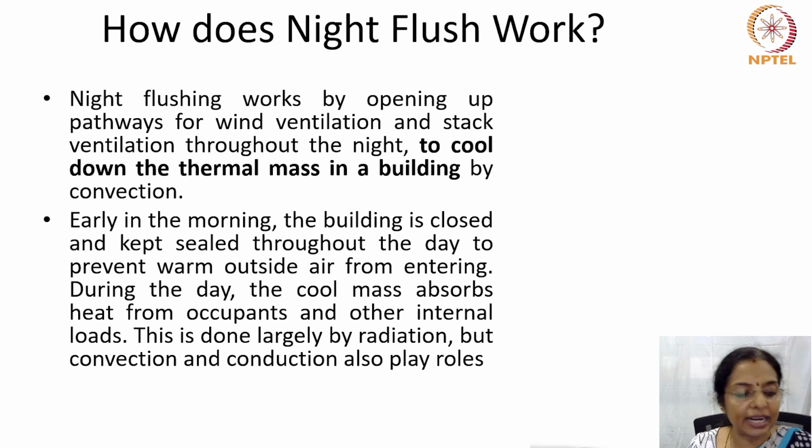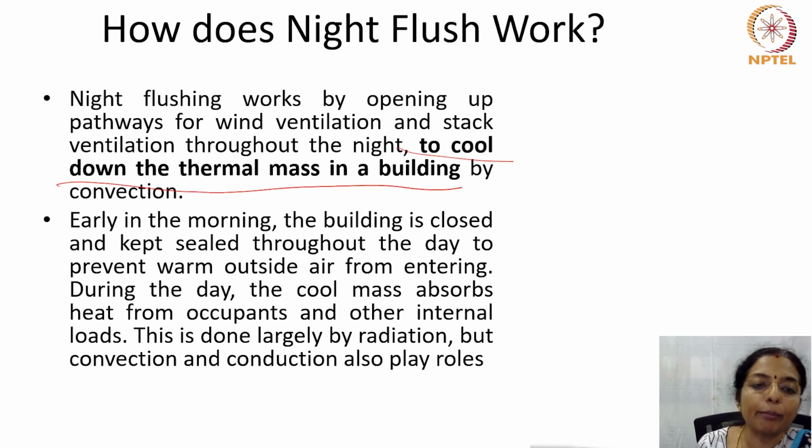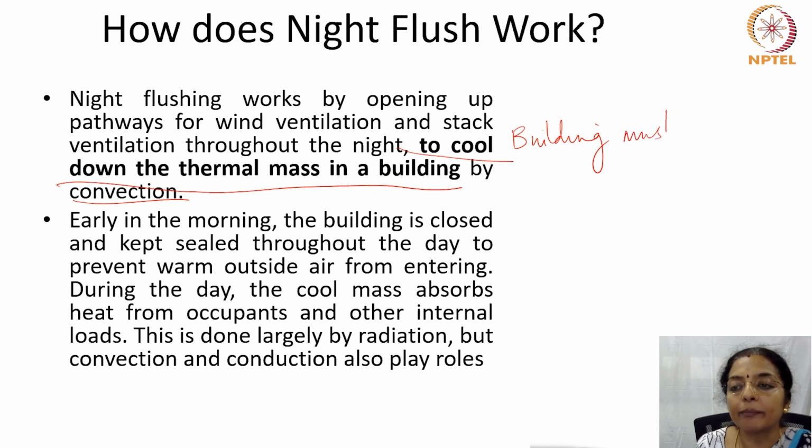So how does night flush work? Night flushing works by opening up pathways for wind ventilation and stack ventilation throughout the night to cool down the thermal mass of the building by convection, which means the building must have a considerable thermal mass. Only then this technique will be effective.